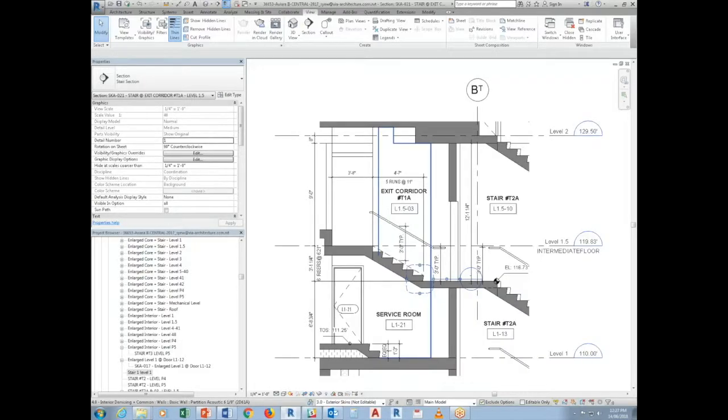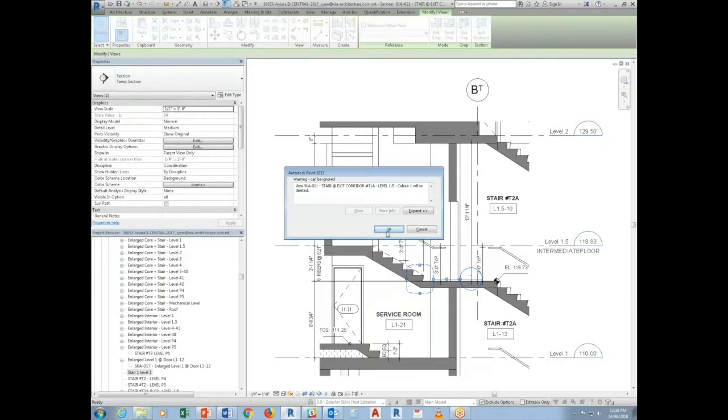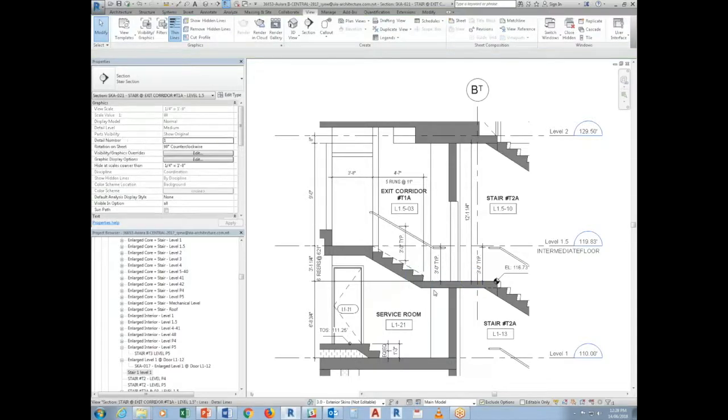But once you get into more repetitive objects, that's where callouts should not be used, because you can get into very difficult places to find where this callout belongs to, or where that callout belongs to. The one way I typically do it for callouts is referencing. I'm just going to get rid of this, okay? Now, one thing you notice is that every time I delete that callout, that view gets deleted.